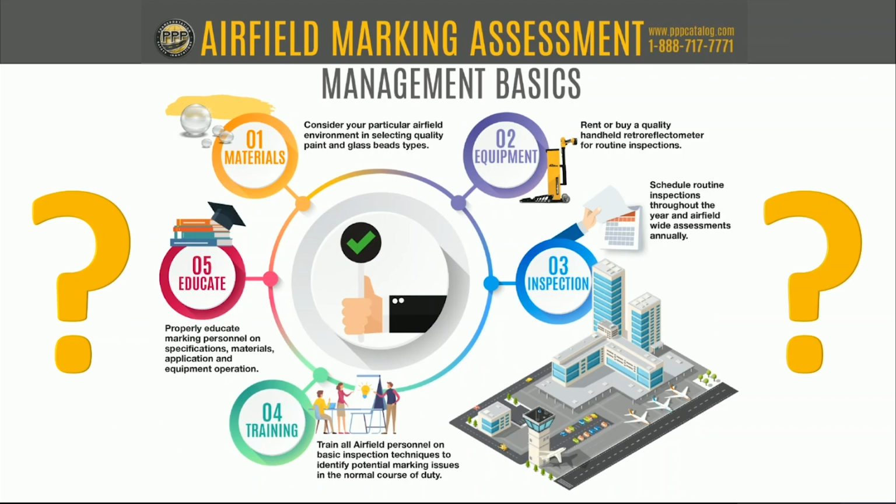So one of my favorite things to put in there is the marking equipment, especially if it's a runway project or if there are wider markings involved: the marking equipment must be able to apply a 6-inch to a 36-inch line in a single pass. That essentially is specifying truck mounted equipment. It's really important. You do not want to see a small machine painting a 30-foot wide by 150-foot long aiming point marking on the airfield. They'll be there 2 weeks from now. So, that's one thing that you can do.